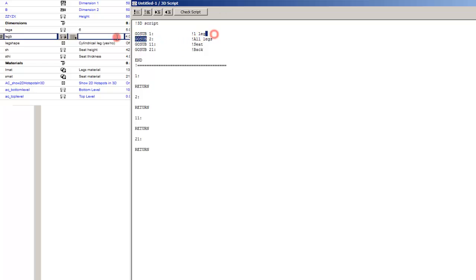And since this subroutine 1 will create one leg, I will use it in subroutine 2 for creating the separate legs. And in subroutine 1 we will create one leg, which will be prism, and you type the legs. Just prism and use the coordinates of the legs. In this case will be the dimensions leg A and leg B. And let's type the dimensions.